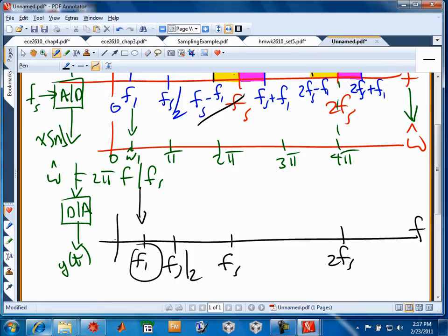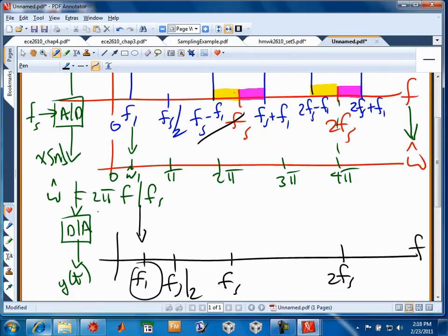In certain applications of sampling theory, that's workable. In most applications, it's not. In certain communication signal processing scenarios, that's actually a desirable feature, and I'm not going to try to explain that right now because I don't want you to get confused to think that aliasing is necessarily a good thing. For speech signals, it would not be a good thing at all, because it would mean that our speech would sound all garbled up. Spectral content would be shifted to different locations, and I guess thinking of a science fiction movie, you'd sound like an alien talking or something if your spectrum was all shifted or inverted around. Hopefully I'll give you a demo of that.